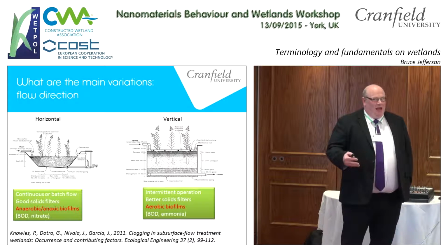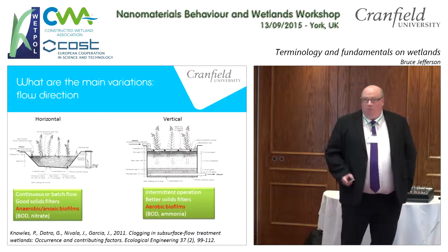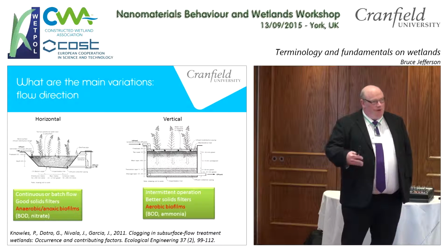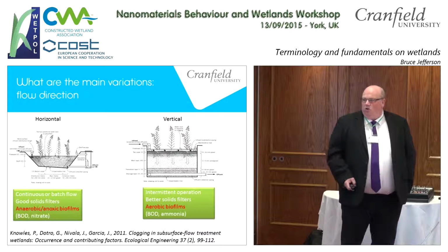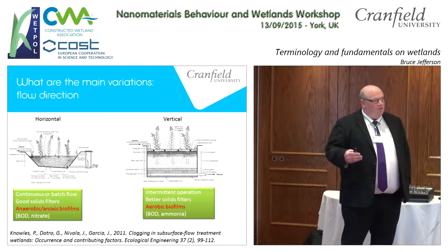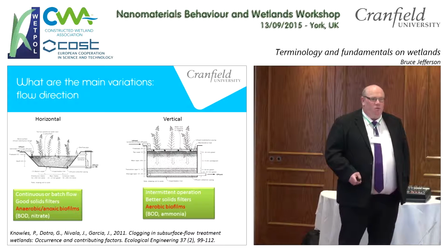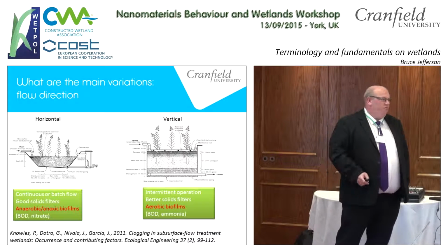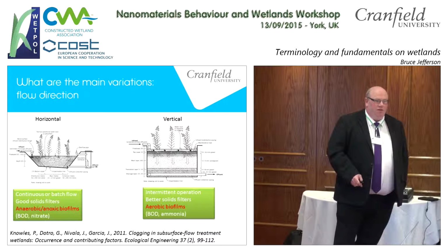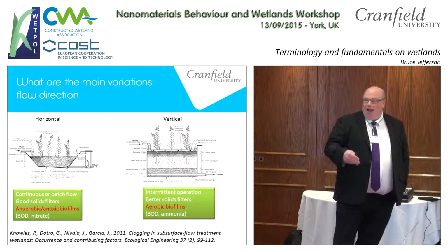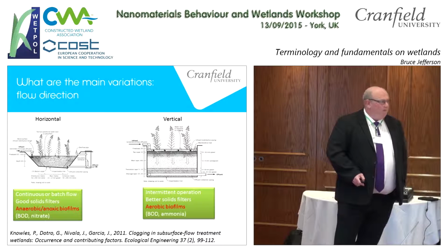And generally provide enough oxygen. You operate them to make sure enough oxygen is getting into the sewage so that you're driving those aerobic biological processes. Whereas in my horizontal flow wetlands, there's no real oxygen involved. The very top layer of the water will get some oxygen through mass transfer from the surface, but it's not enough to meet the demand of the biology within the system, so it's going to remain anoxic, anaerobic.